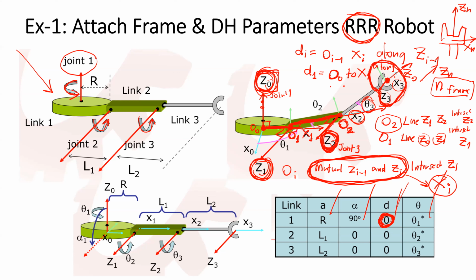Another choice is to make it easy. Just use the Z of the end effector frame to be in the same direction as the link before it, so that when we compute the link twist, or the angle between the axes, it is still 0 in the matrix. So for the final frame, you have two possible ways to do it.